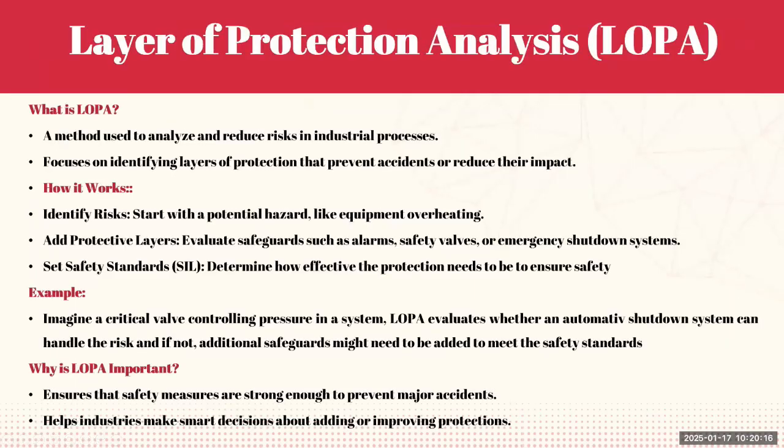Then we have the layer of protection analysis, which is the LOPA. So this is a key methodology in risk management. So what is a LOPA? A LOPA is a method used to analyze and reduce risks in industrial processes. It focuses on identifying multiple layers of protection that can prevent accidents or reduce their impact if they occur.